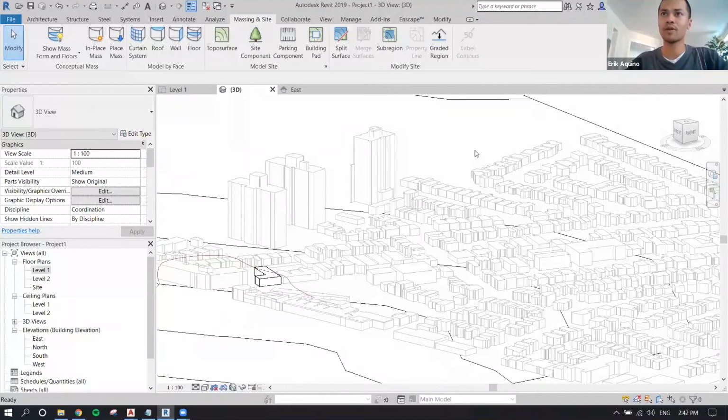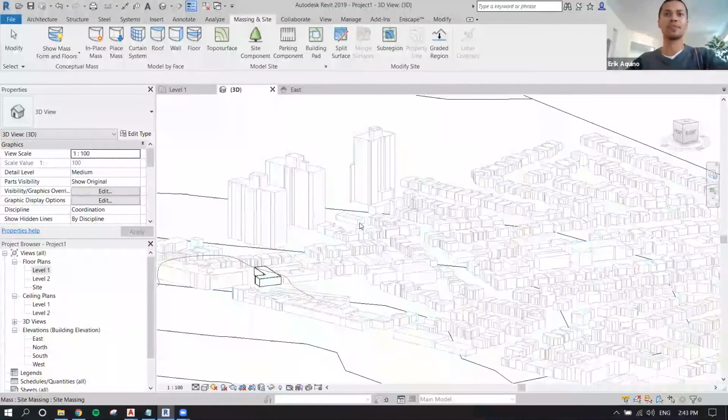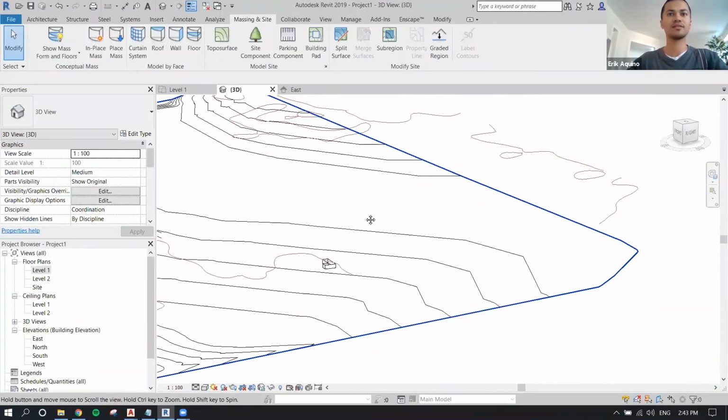Okay. As someone asked before, how can you edit 3D massing once you've placed it in Rhino? So if that's your intention, then you don't want to link the massing, because you're just referencing the information from that file, bringing it into Revit and letting it sit. If you want to have it more editable, you'll want to import that massing file. And from there, there's an option to explode. So I could show you what that looks like for your own benefit.